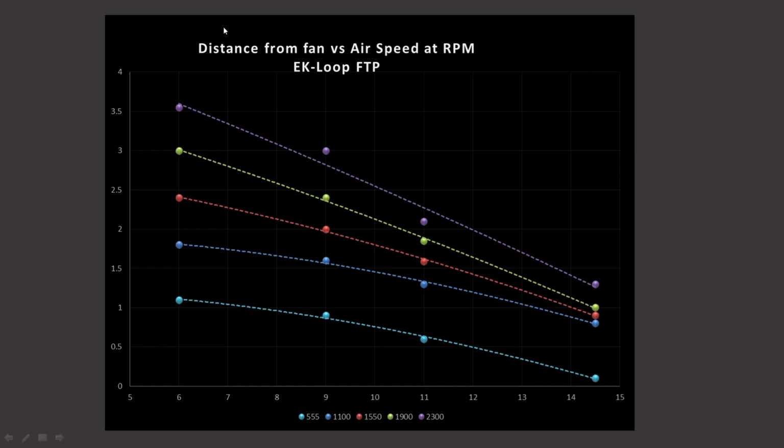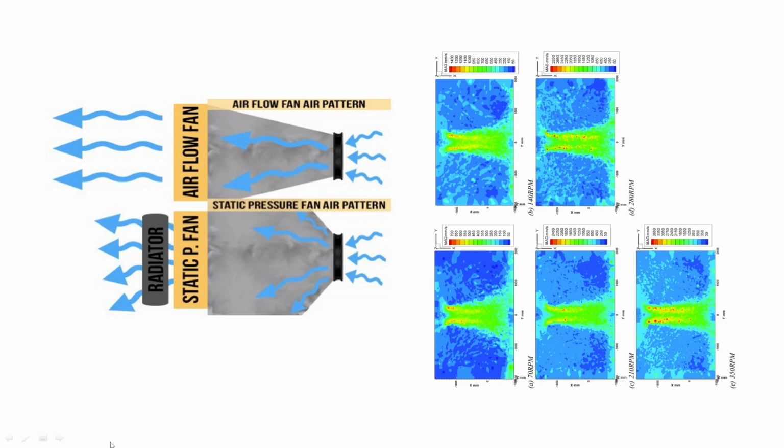The other way to look at it is, how good is this fan at actually blowing air? What you don't want to see is a fan that all of a sudden has a steep drop-off and levels out. So, just some very basic diagrams. As you run your fan and you're pushing air, there's air in your case. And the air in your case is trying to slow down that central column of air. So you'll never have a perfect cylinder of air traveling down at a constant speed. It'll always slow down a bit.